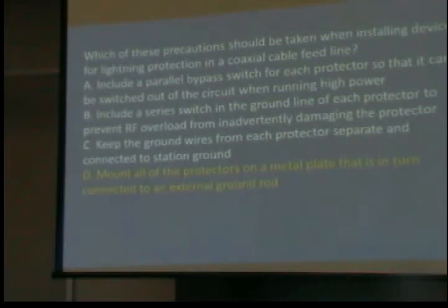Okay? I ground my generator that way. Now, when you're saying bring this in with the lightning protection, you're saying to put one of the wires through the plate? Yep. I actually have what's called a pass-through on there that I screw a coax onto on each side. Piece of plate, drill some holes, put the pass-throughs in.